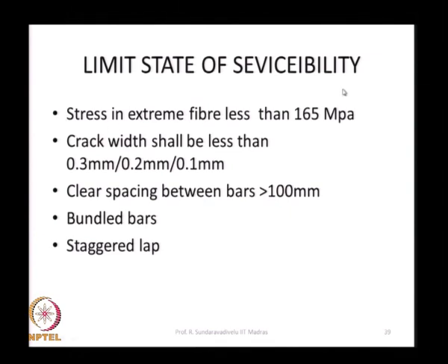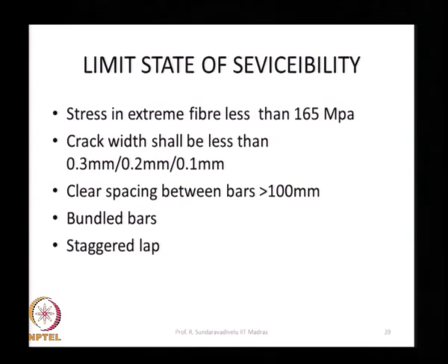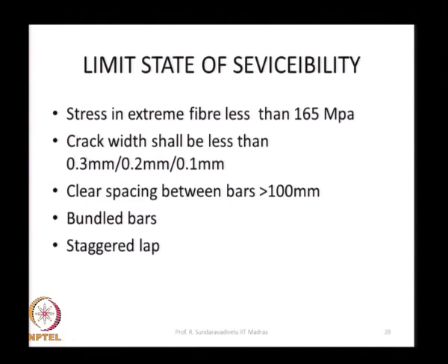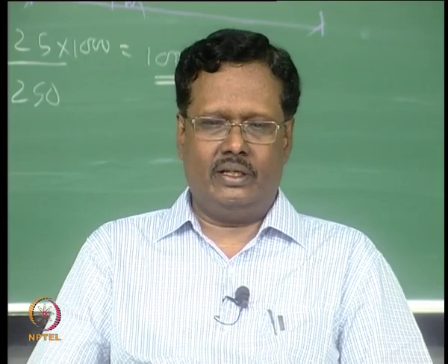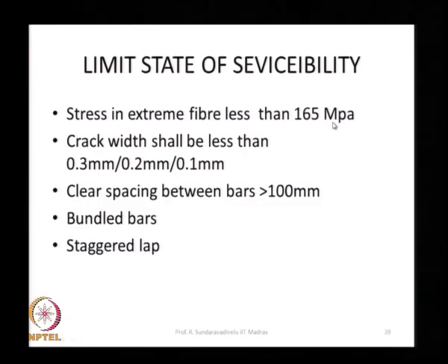See, for limit state of serviceability, there are 2 cases that are given. One is the crack width, another is the deflection. Deflection should be less than L by 250 or L by 350 depending on various conditions. The crack width means whenever there is concrete, the concrete will crack. You cannot say that the concrete will not crack, it will crack because there is a lot of stress that the steel will take. Steel will take up to 165 megapascal. This is the allowable stress, whereas actual stress will be 500 megapascal.